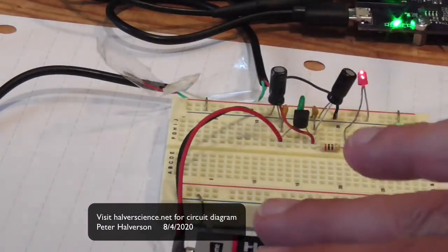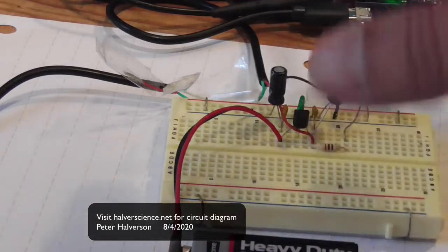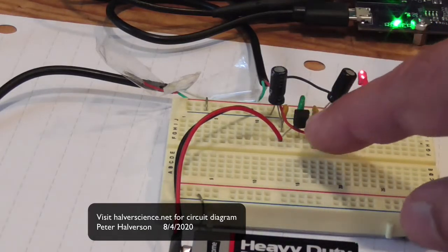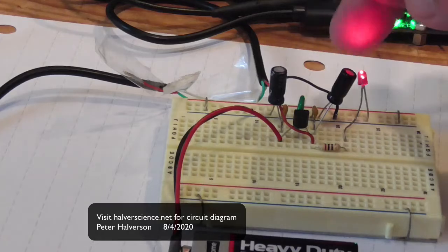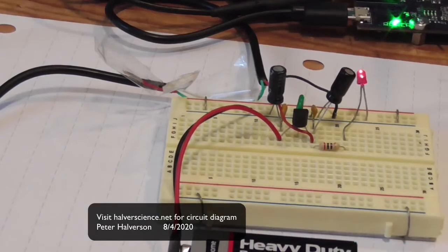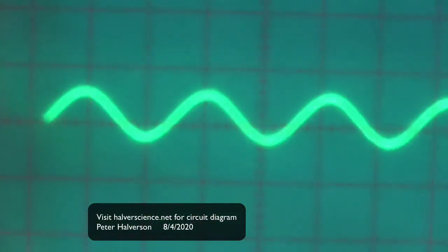Instead, the power is coming from this battery. It's 9 volts, and this thing wants 5 volts. So the 9 volts is turned into 5 volts by this little voltage regulator, and from the voltage regulator you're going to the red and black wires, which then go to the FPGA board. So now we have a satisfyingly clean signal coming from our FPGA board.